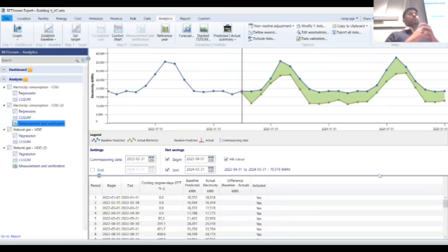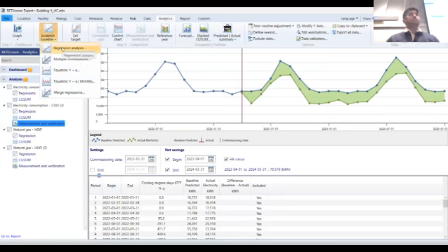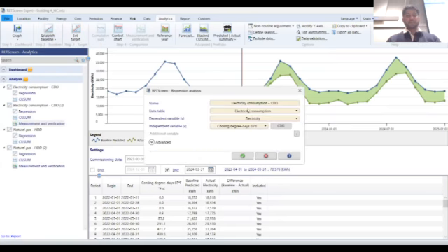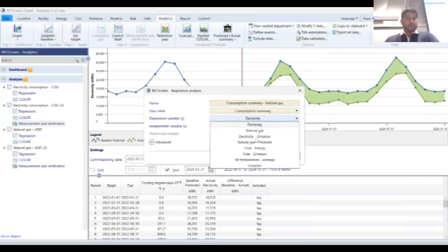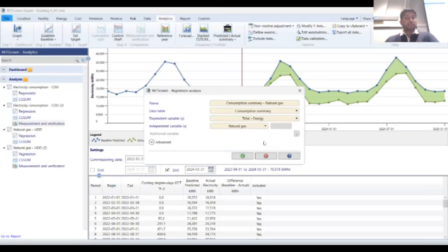What we did was run regression and M&V for individual fuels. We can run it as a property, and I can quickly show you that too. Again, same procedure, regression, but this time I don't want electricity consumption, I don't want natural gas, I want consumption summary, and I want the total energy. That's my dependent variable. My independent variable is going to be air temperature average. That's what I'm comparing it with. That's what's affecting my total consumption.